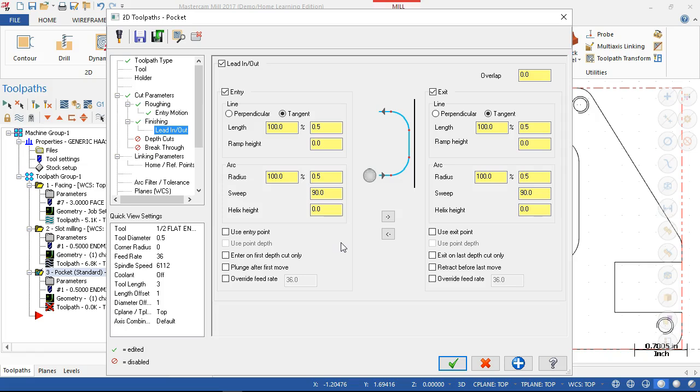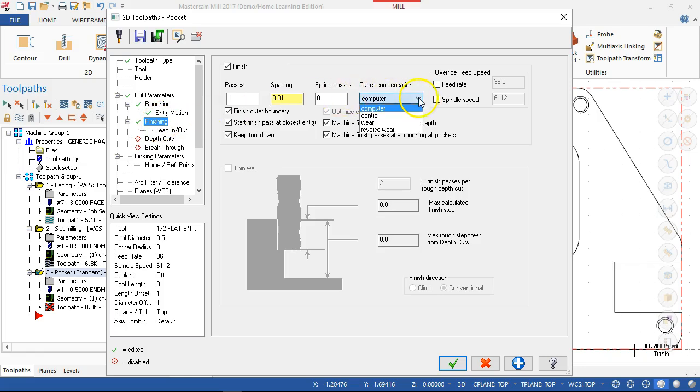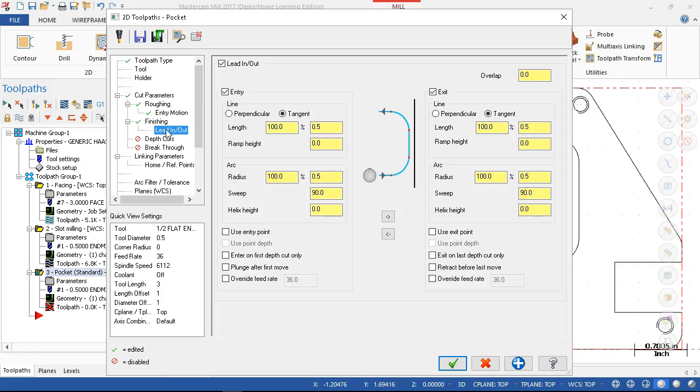The other consideration is if you are in the mode where you have to enter the value of the tool diameter in the control, then the rule is that you need a little more than the radius.